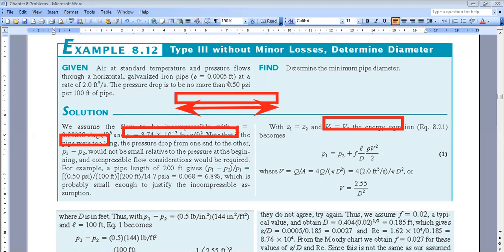Of course you know that, logically, a reduced diameter will increase losses, because you are restricting the cross section, which will cause more losses. You can also see this from the expression. The major losses are equal to f times L over D times rho V squared over 2. So D is here.